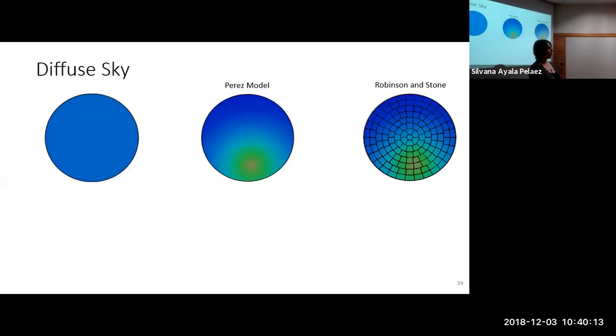Well, I was even thinking about the nearby structures, when you have the panels. A single panel is easy, but if you have some diffraction from the nearby structures, we'll have some reflection for sure. Yeah, so it does consider that. The rays get sent out in a 2 pi hemisphere, and they specify how many bounces they will have, or until which amount of energy they will just fade. Depending on the property, they will absorb some part and reflect. And for no reflection, you can put scattering too, which is pretty neat.